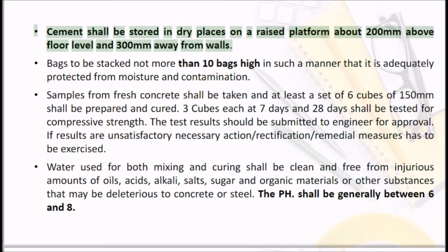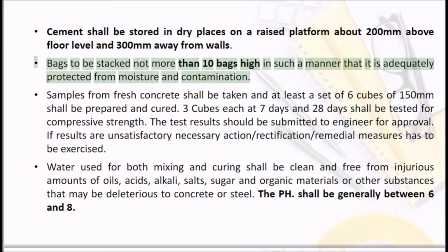Cement shall be stored in dry places on a raised platform about 200 mm above floor level and 300 mm away from walls. Bags to be stacked not more than 10 bags high in such a manner that it is adequately protected from moisture and contamination.